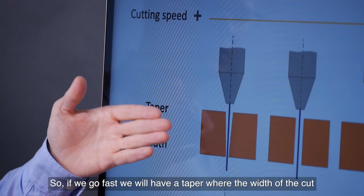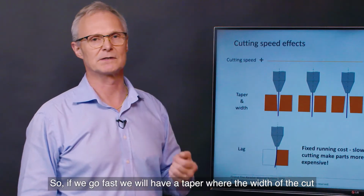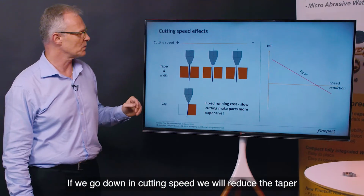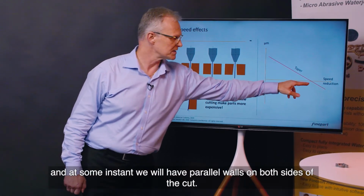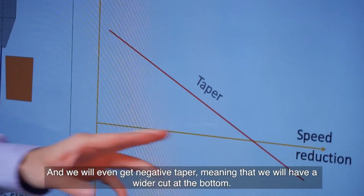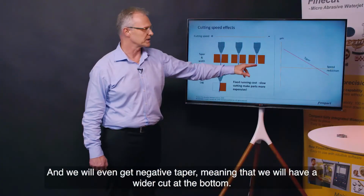So if we go fast, we will have a taper where the width of the cut at the top is wider than the cut at the bottom. If we go down in cutting speed, we will reduce the taper, and at some instance we will have parallel walls on both sides of the cut. And we will even get negative taper, meaning that we will have a wider cut at the bottom.